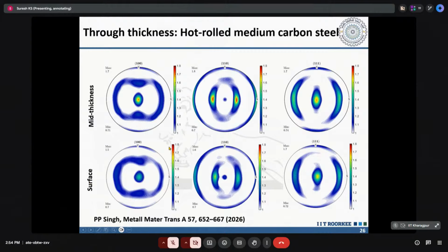However, the role of these shear effects at the surface, which give rise to changes in the alignment or evolution of the preferred orientation, also sometimes becomes important to understand how this deformation is happening. Otherwise, one has to polish the sample up to the mid-thickness region.